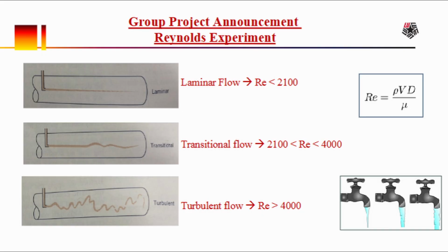While the laminar and turbulent flows were clearly different and distinguishable, the transitional flows were more difficult to identify, as it can appear similar to turbulent flow, especially due to the difficulty injecting dye smoothly. It was more of a jerky, rapid insertion at some points, although you could still see the fluid behavior after the injection point.